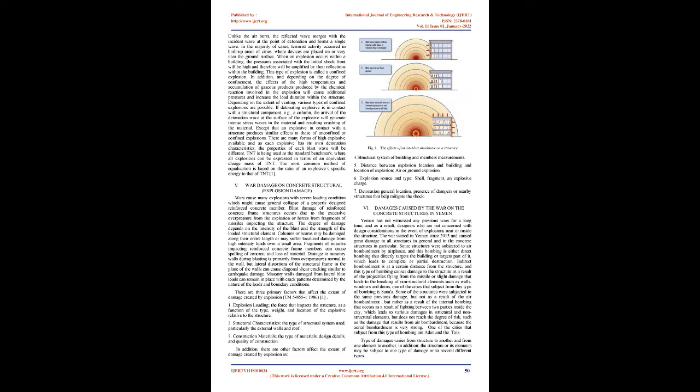If a detonating explosive is in contact with a structural component, e.g., a column, the arrival of the detonation wave at the surface of the explosive will generate intense stress waves in the material and resulting crushing of the material. Except that, an explosive in contact with a structure produces similar effects to those of unconfined or confined explosions.